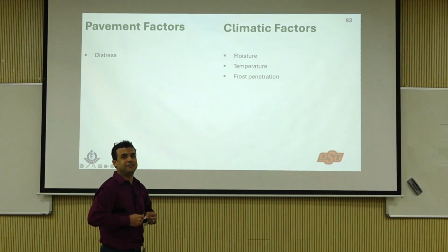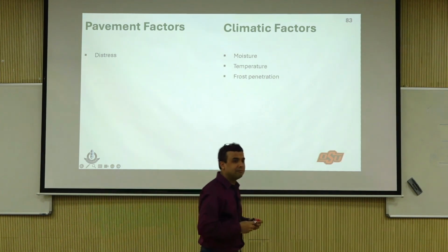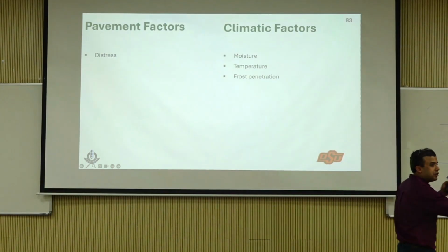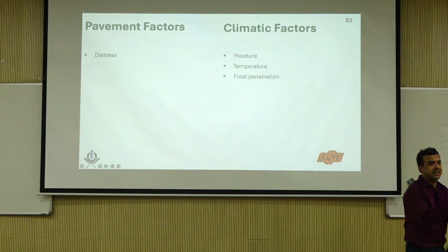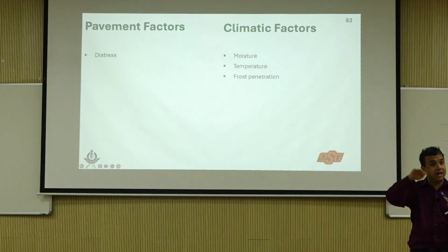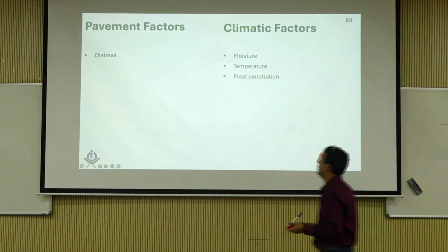Either one is a good answer. Exactly. Because the basin happens because of the load transfer, right? If there is a crack, the load may not transfer. You may actually think, oh, it's really good pavement, but it's actually because of a crack that it didn't transfer, right? So it's very important.